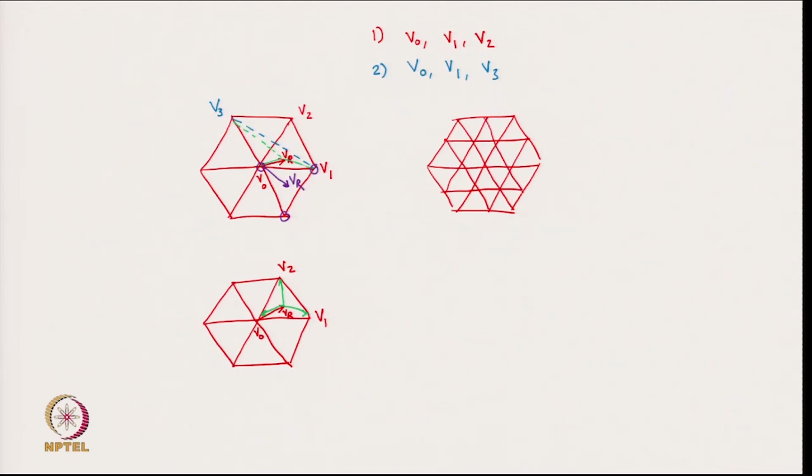For example, this is the space vector diagram of a 3-level converter. If you see these two diagrams, the boundaries remain almost the same in both cases, but now you have space vectors which are denser, closer to each other as compared to the 2-level.